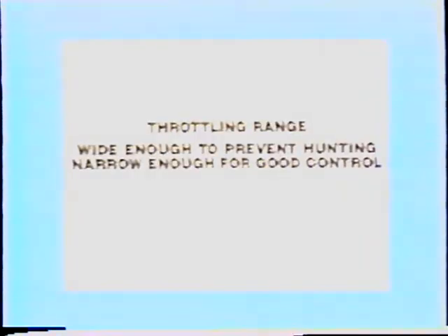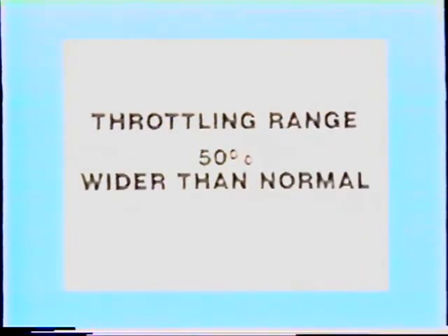When determining the optimum throttling range for a controller and the timing adjustment for the associated integral relay, some judgment and experimentation will be required. Always set a controller's throttling range wide enough to prevent cycling under any load condition. A control loop is least stable under a light load or when the lag time of the process being controlled is short. A rule of thumb for setting up a controller is the throttling range should be approximately 50% greater than normal when the integral relay is to be used.